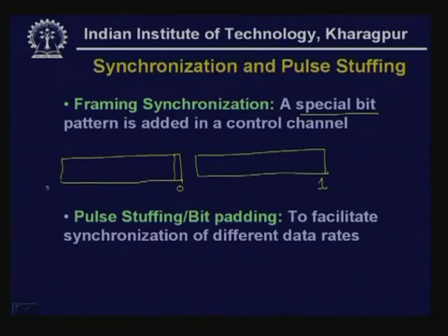In this way alternately ones and zeros are added for the purpose of synchronizing a frame. Essentially these synchronization bits state that this is the beginning of a frame, and the data from different slots are coming from different sources, and they are demultiplexed at the receiving end.